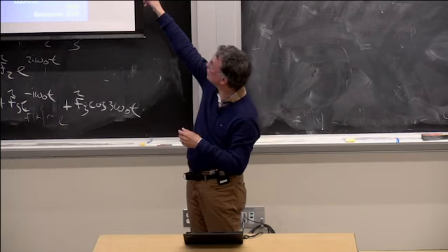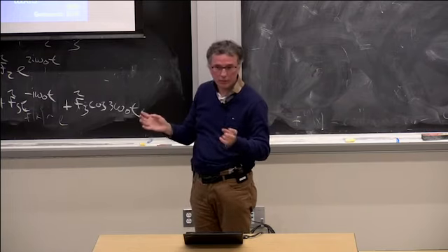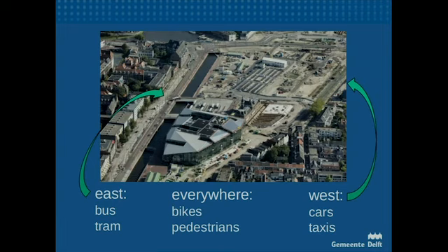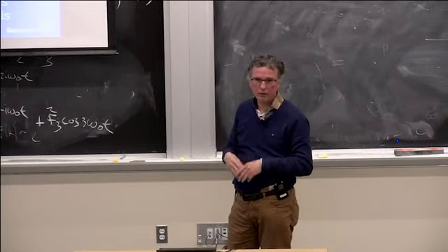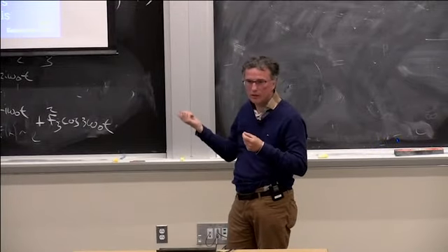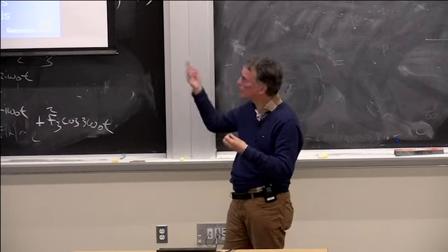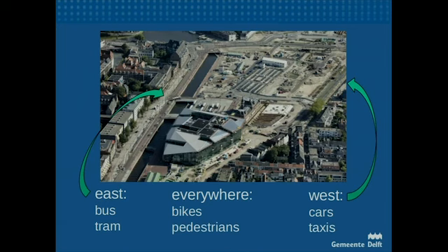And the other intersection is almost fallen off the picture on the right side. That is my car intersection, where all the light rail traffic only has to cross. They go straight through. So it was much easier to handle if I separate public transport and car transport on different intersections. And my transport engineers who were interested in traffic lights, I took them, let me have a look at this design. Can you build a traffic light for this location? Because the alternative was one big crossing with everything, and that didn't work.